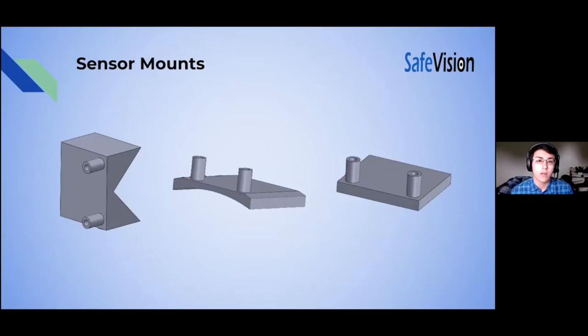To mount the sensors on the arm, we designed and 3D printed 3 different types of mounts. These mounts correspond to different parts of the arm and head that the sensors are attached to. We attach these sensors to the arm using mounting putty, specifically because we're in the prototyping phase. This mounting putty is strong enough to adhere the sensors to the arm during motion, but also easy enough to take off without residue, so that we can move them around the arm freely. We also use zip ties to attach the shielded wire to the arm so that we can minimize the downward force on the mounts, because the wires are very long and heavy.